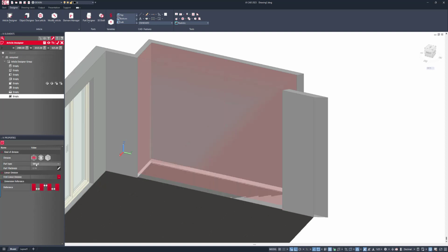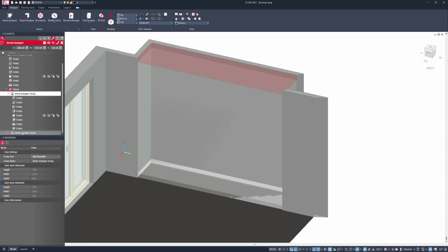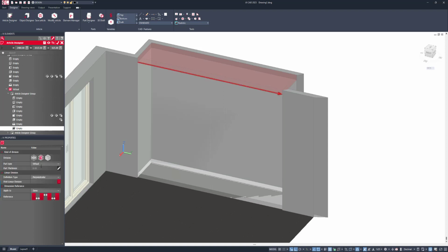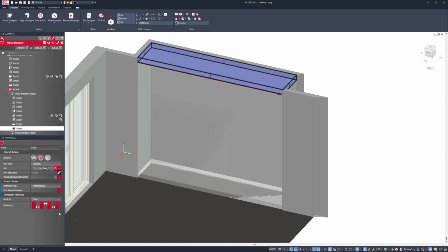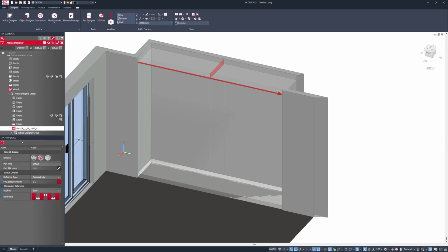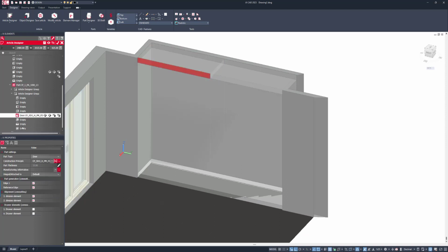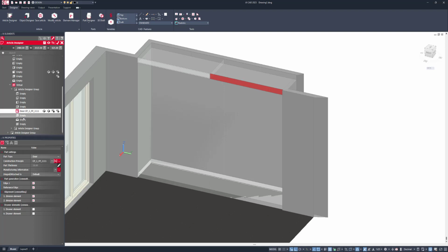I then need to put in my fillers, so I'm going to use a linear division of 1 to 100 millimeters, and that's going to give me my top zone, which I can then divide in half. So I'm going to say that that should use a partition, and 1 to 1 would give me an equal split. That partition should be virtual though, and then once I've got my two zones, I can open the zones up and I can then add in my filler panels. So let's copy those into the two zones and paste.